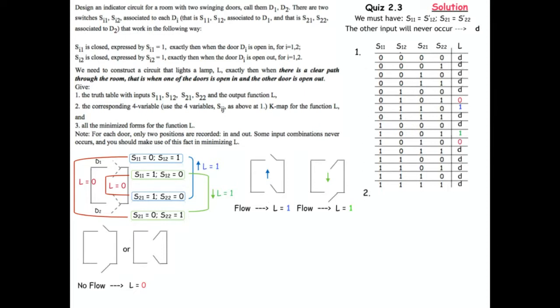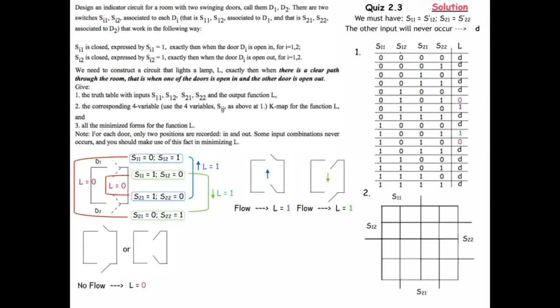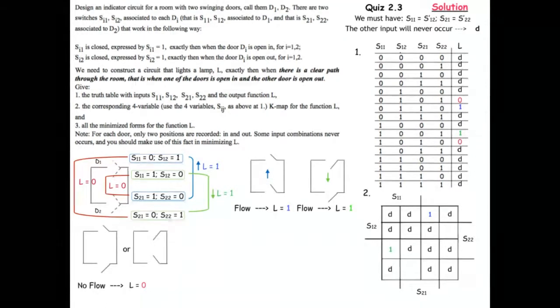So now we're going to attempt, through a K-map, to come up with some kind of fewest, largest prime implicants, and then figure out the minimal form, the simplest way to build the circuit. So we only have 2 1s, and because we only have 2 zeros, well, we could put them on. Usually we leave zeros as blank squares, and then the rest are Ds. And now we're going to do prime implicants. Ds can be covered by prime implicants, but they don't have to be. The 1s must be covered by prime implicants. So let's see.